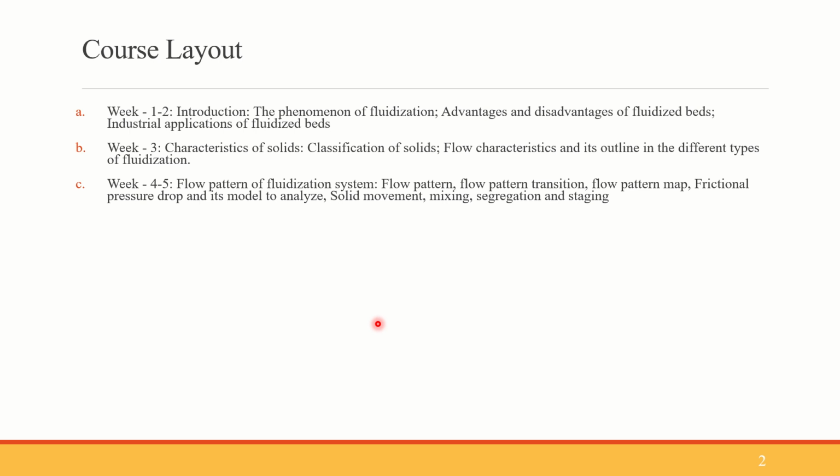So, after minimum fluidization, with increase in the velocity, we are able to observe the constant pressure drop and the particles also start to move inside the bed. So, there come up various regimes. The first one is that if we use liquid as a fluid, we can see smooth fluidization happening. There would not be any bubble formation.